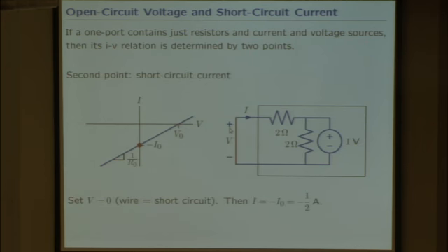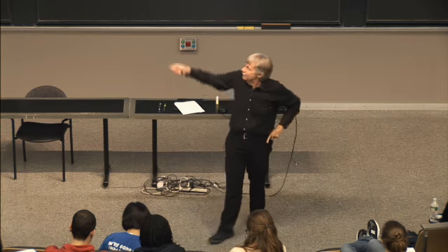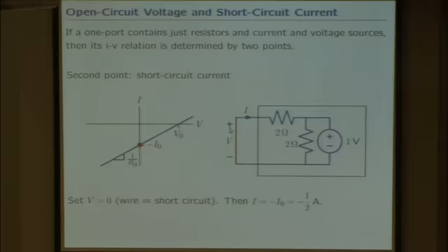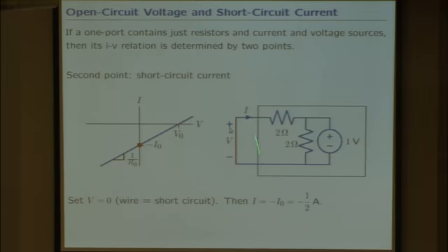So I'll find the short circuit current. Imagine that I put a wire between the input and the output, and I'll compute how much current this circuit generates in that wire. Again, the only confusing part is that the reference directions are backwards to the way you might have expected them to be. If I put a short circuit here, then the voltage between these nodes is still 1 volt. That's what the voltage source always says. So the current that flows through this wire, the short circuit current, is just this V over that R, except it's in the negative direction.